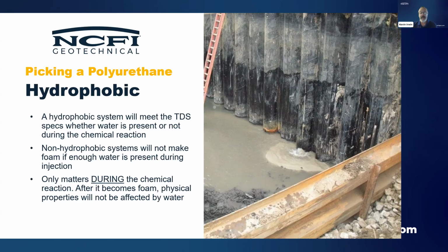But after the fact, after it's foam, hydrophobic doesn't make a difference anymore. It doesn't apply here. After it's foam, closed cell foam is a moisture and air barrier. So hydrophobic systems are going to be really useful when you're shooting directly into or around water.